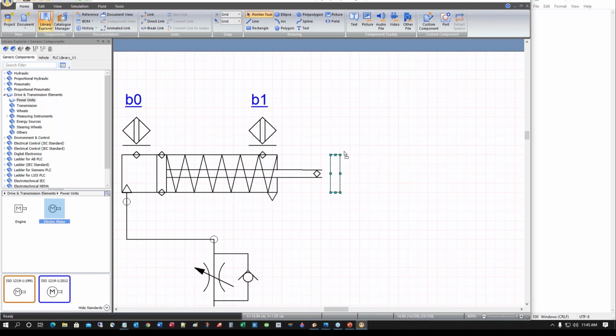This is the snapping. Now to control my snapping here, and this is going to be very important to understand this concept, you're going to see that at the home ribbon, there is the snap section. There's two types of snap. The first one is the component snap. Component snap relates to the components, which are these components. Now the drawing snap is related to these objects, to anything that is in this section. The snapping is done using this kind of snap. So you see both of them are by default snapping to the grid.